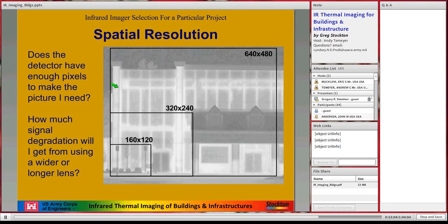If you've got an old infrastructure, you've got leaks. If you've got a hot water loop and you can measure everything really well, you can tell about what your leak is, but you can't tell the difference between steam or anything. You really can't. If you know you have loss, and everybody does, you can't tell how much of it is a leak and how much of it is just bad old piping. So if you've got really bad old pipes, you're going to have to eat it, because replacing them just costs a fortune. But if you get an infrared survey done, you will find the leaks, and those have got to be fixed. There's no question about them.